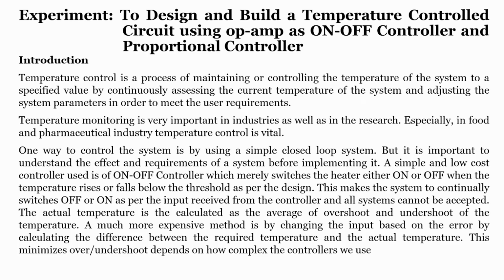What is the logic behind that, what are the design parameters, and how is it heating the plant? We will take a temperature sensor on top of the plant because we require to measure the temperature on top of the plant. Since temperature is a physical phenomenon and we are implementing a controller using analog circuitry, we require an electronic input. Electronic input is nothing but either voltage or current. So, we have to take a transducer or a sensor which converts a temperature change to an electronic output voltage.